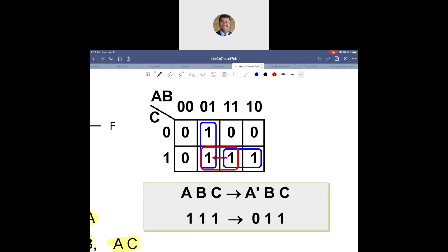So you take the logic expression and you translate that into a K-map, an SOP K-map, right? You are focusing on the ones, you are grouping the ones. That guy is what? This is A complement and B. This guy is A and C. So that was given to us: F equals A complement and B or A and C.